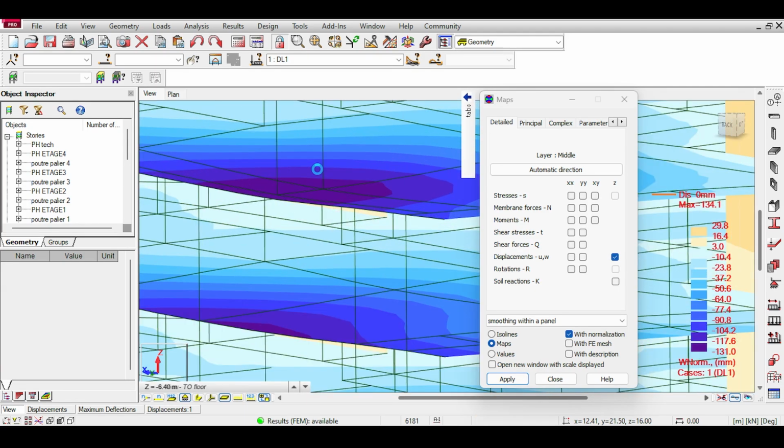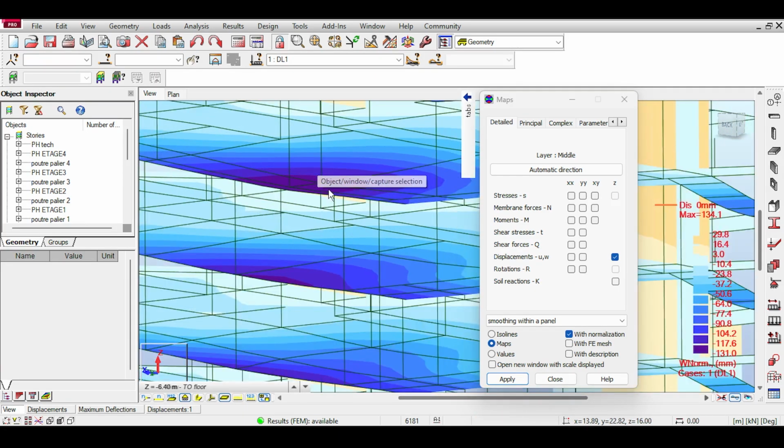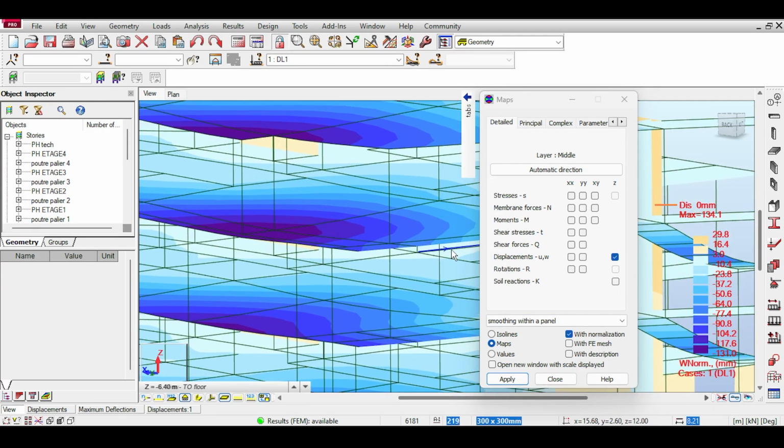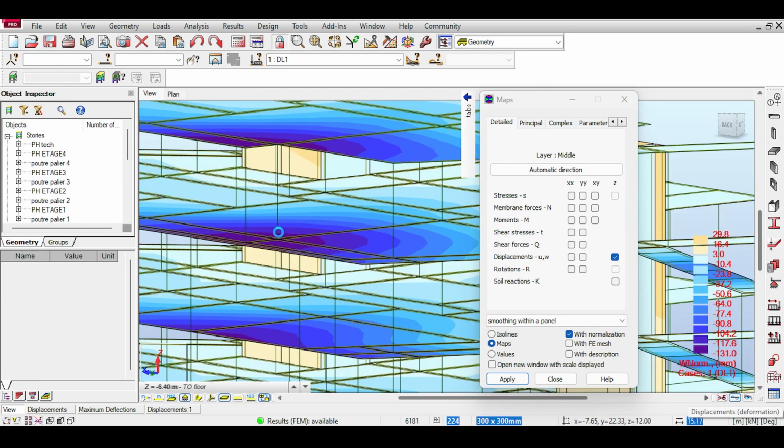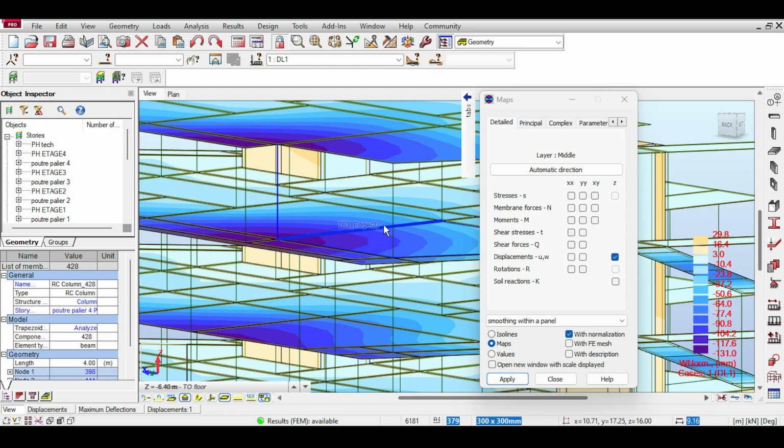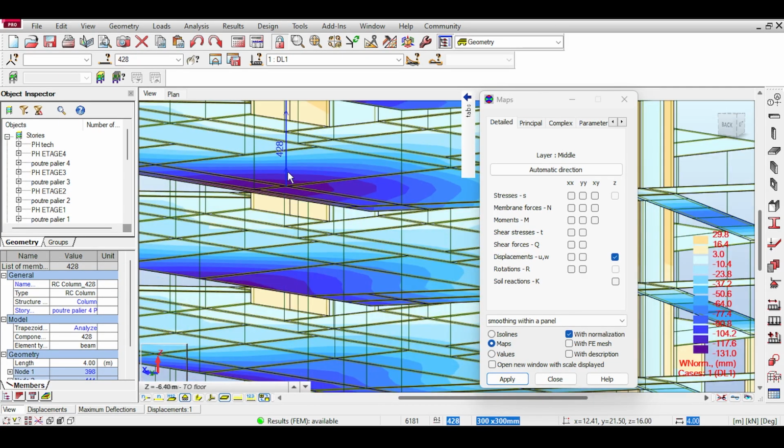Now, if you want to discontinue a column, that's okay, but you need to strengthen the beams that carry the discontinued column. I don't know about the architectural drawings here, or what was actually intended to be done, but my immediate piece of advice for our dear engineer is: if you discontinue the column, then you need to provide strong beams, and if you want to continue the column all the way to the ground, then this problem will be solved.